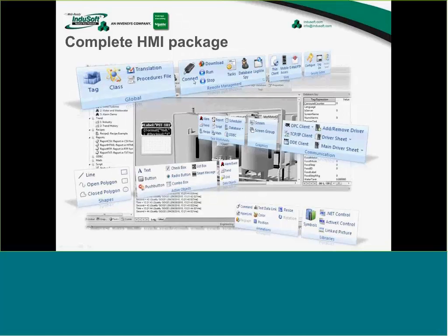We also have remote tools to be able to connect to a remote device or remote HMI, and start, stop, download, and troubleshoot that remotely. So that's a real handy tool rather than copying and pasting to a USB stick, moving it over to the other device, copying and pasting, etc. This allows you to connect to it, stay connected, and if you make changes, it can automatically update the remote device while it's connected, which is kind of nice.